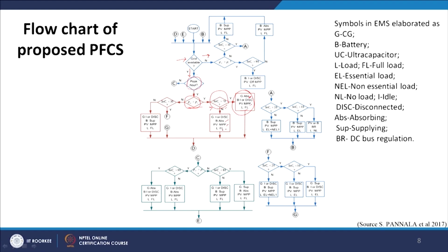I repeat, if the storage is more than 70% for you and it is peak hours, and the PV is also greater than PL, then certainly it is my role to support my grid. So, I can give that excess energy available to me to the grid, because the grid is struggling with peak hours and I can support it.